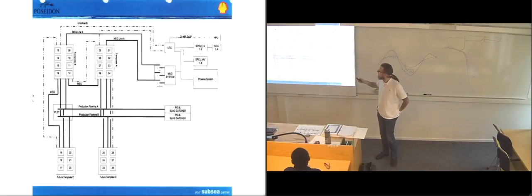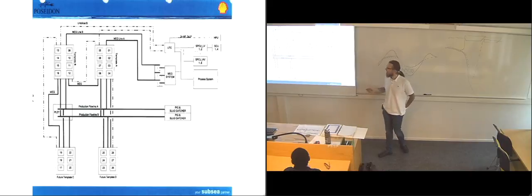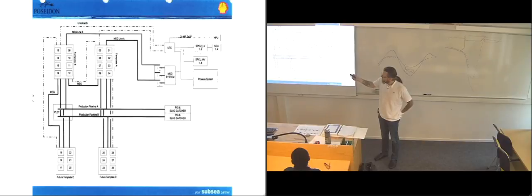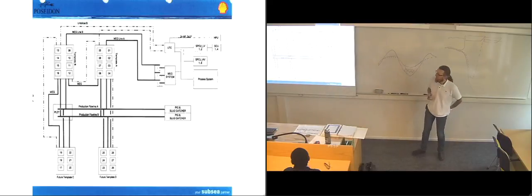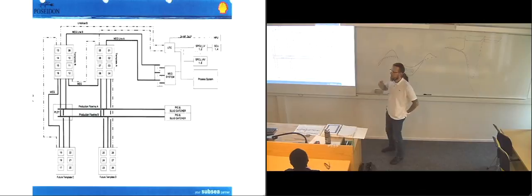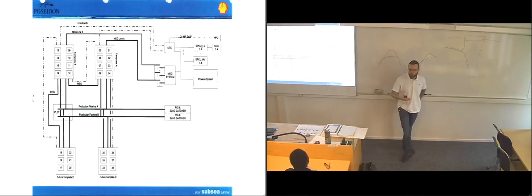And here you have the methyl ethylene glycol system, which is the injection system that they're using. And they inject it down here, and then they inject it into the flow. So it's going into the different templates, and it's connected over to these future templates also. But it's actually injecting this methyl ethylene glycol, MEG, into the production flow.